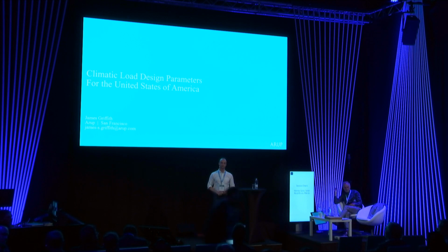Because, of course, since Feldmeier did his studies, IGUs have developed. And in the actual situation, if you do a design in Germany for a state-of-the-art IGU, you no longer calculate just with the 20. Usually you have plus 29 degrees centigrade. I'm not sure about the state of the art of IGUs in the US, maybe.